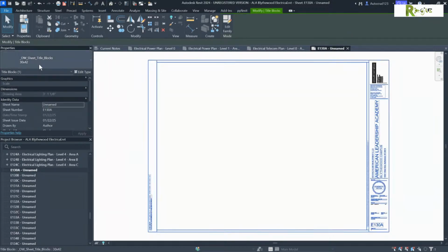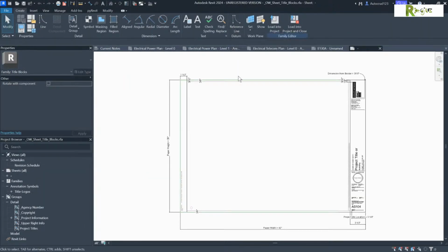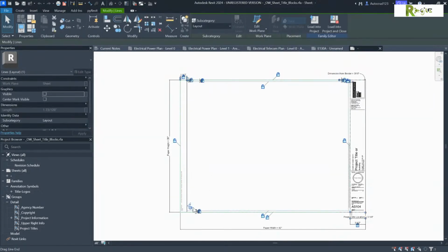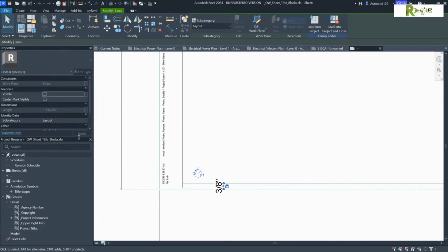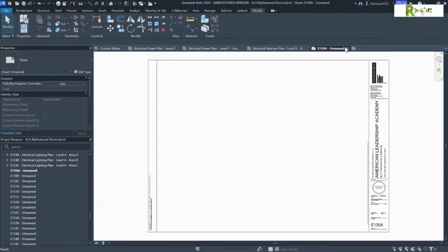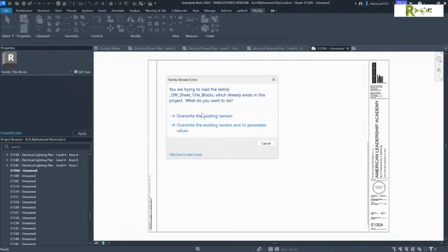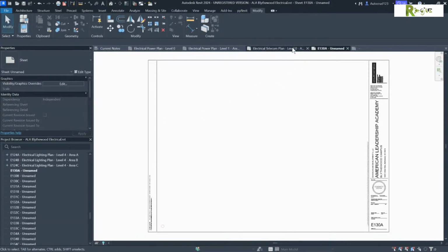Is there a visibility checkbox on there? No. Double click and say edit family. Up at the top in the middle, right below the word add-ins. There you go. Click on that purple circle down in the left corner and turn its visibility on. And then push him back into the job. You could have closed them, but that's fine. All right, that purple square.